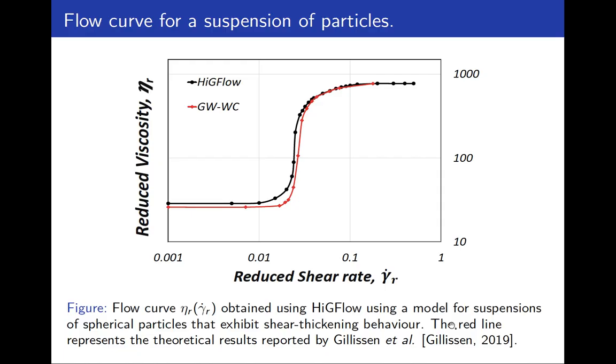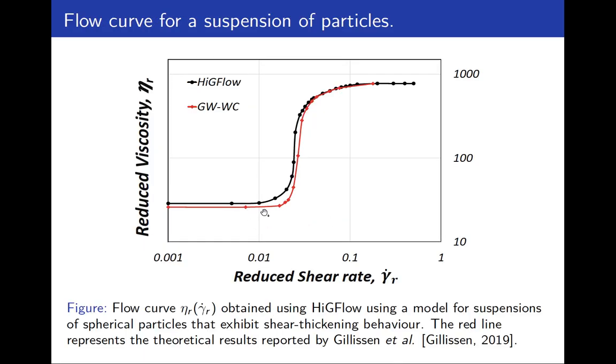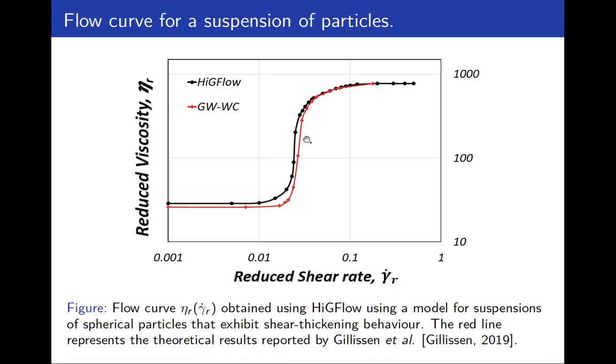And then for a suspension, we observe this kind of behavior where we report the viscosity versus shear rate. The viscosity is very small when the velocity values are 0. But when you deform the material, when you increase, let's say, the velocity, you will observe a rapid increase of viscosity of the suspension.